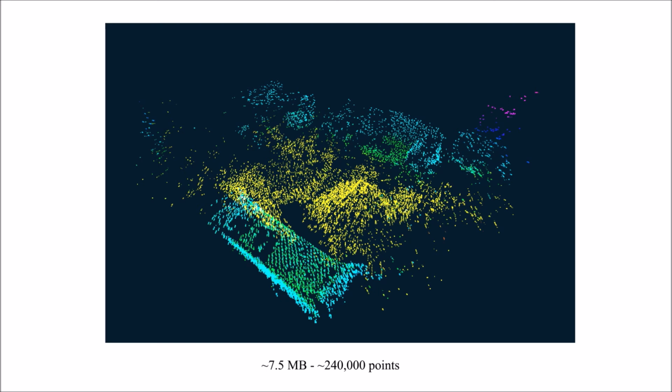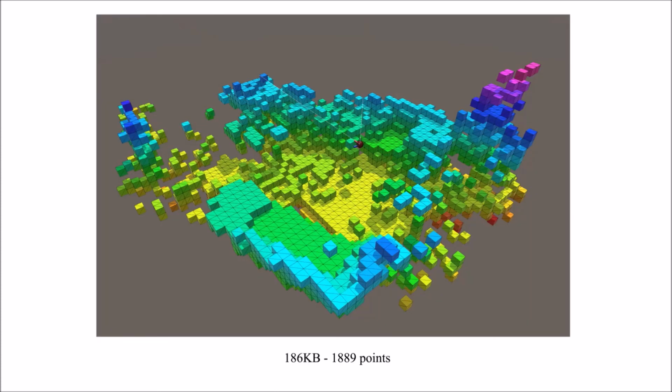To process it, we divide the world into chunks. Each chunk covers a 1.6 meter cube. Each chunk contains a 3D map in it. When ARKit gives us a new point, we find its chunk and block, and increase the density of this block by 1 unit. We use this density to eliminate point cloud errors. After these steps, this is how our point cloud data looks.